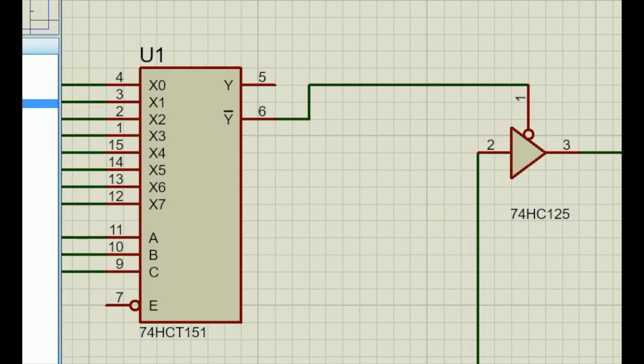This is the catch part of the circuit. Here we are using an 8-to-1 multiplexer and a tri-state buffer. The count of the counter is used as the selector input to the 74151 multiplexer. The corresponding inputs to the multiplexer are the last rows of the red LEDs. If both the LEDs are in the same column position, then the output of the multiplexer is high.